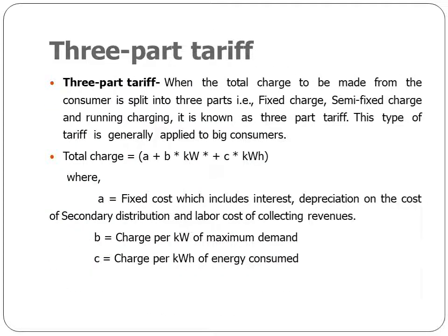Three-part tariff. Three-part tariff is the same as the general equation. When the total charge to be made from the consumer is split into three parts, that is fixed charge, semi-fixed charge and running charge, it is known as three-part tariff. This type of tariff is generally applied to big consumers.